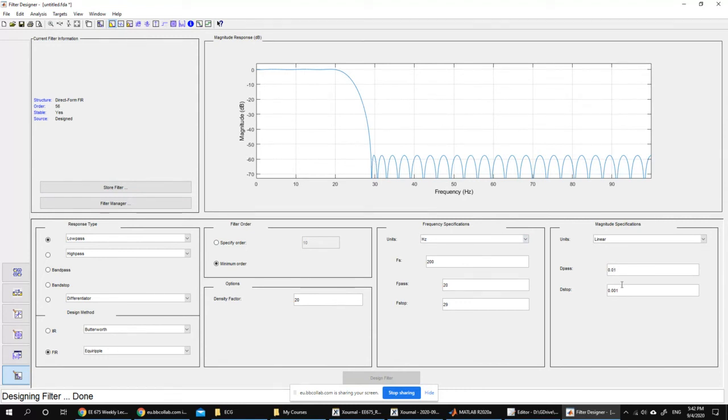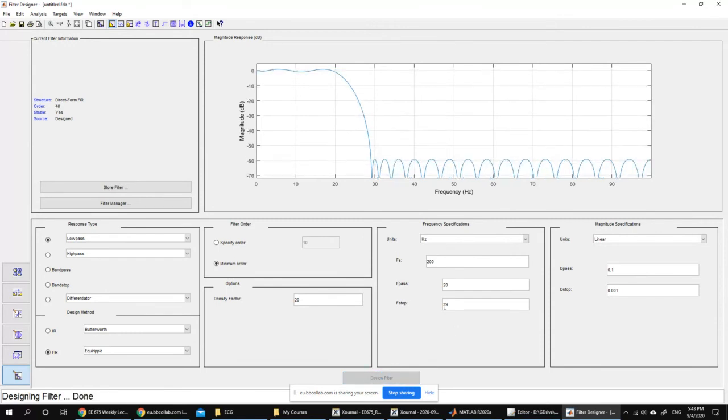Let's try to improve this also. Let's try to just change it to 0.1, like the default value for it. I'm going to allow variations here within 0.1. Remember that the magnitude at the cutoff frequency was 1 over square root of 2 of the actual signal. So it was definitely below -0.1 from the original one. So 0.1 should still be okay. Let's see how that would affect the signal.